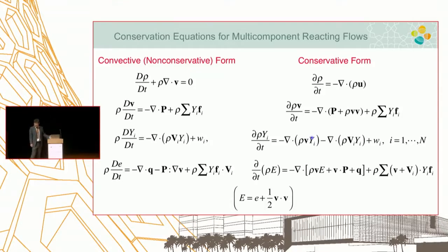So you need to pick the convective velocity of your system, pick the worst-case scenario, and make sure delta t is smaller than that. There is another criterion based on the diffusion term, and another one based on reaction. Sometimes people call it reaction CFL, which is a misnomer. The bottom line is that oftentimes in this kind of integration, the reaction source term is the most demanding one. I'll spend some time on that. I have some points to make, which will follow up in the second lecture.